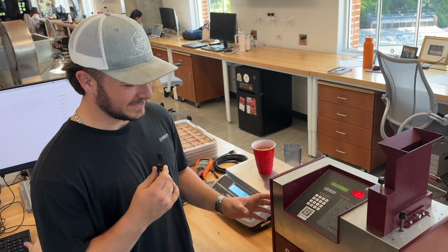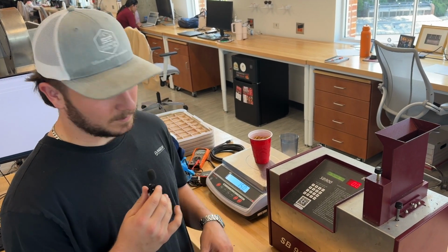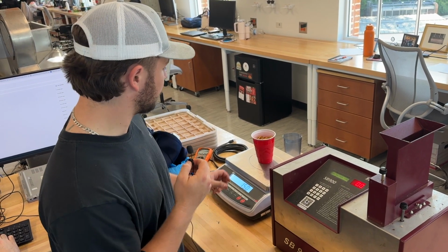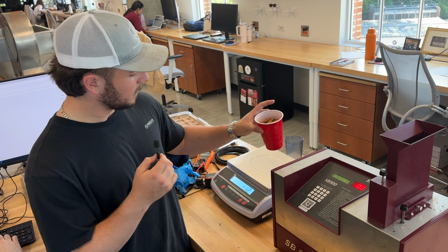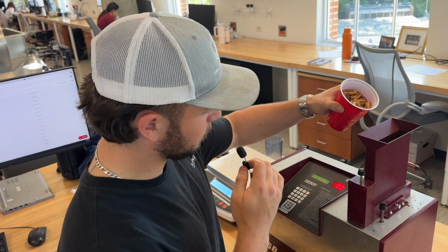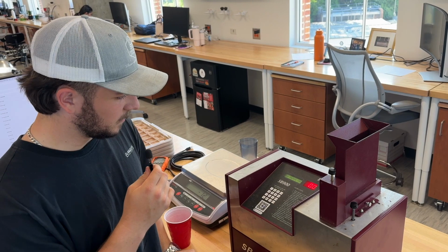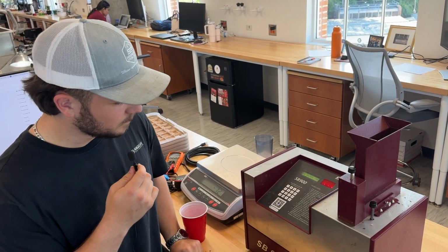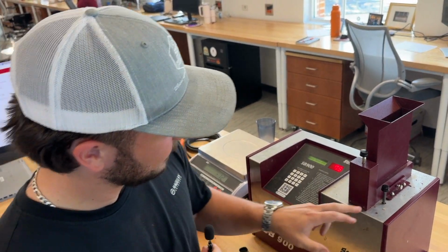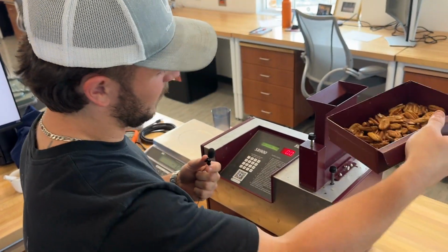So here's our Steinlite moisture meter. Basically, one of the independent variables we've been focusing on for our experiments here is kernel moisture. And so we'll collect here a 150 gram sample of whole halves, and we'll dump them in this little hopper, and you drop it in there, and you wait a second. You see here, this batch of kernels is 7.5% moisture, and so then you just drop it out. It falls in the bottom here into this tray, and we would recycle it.